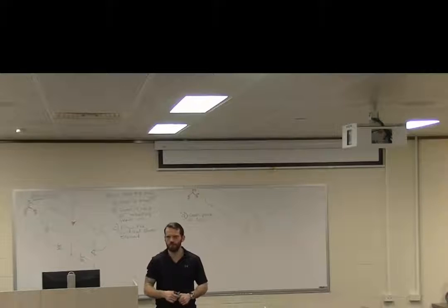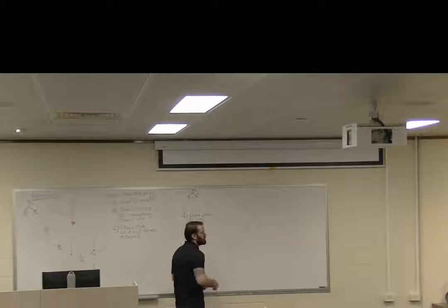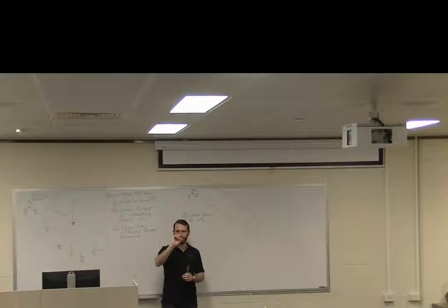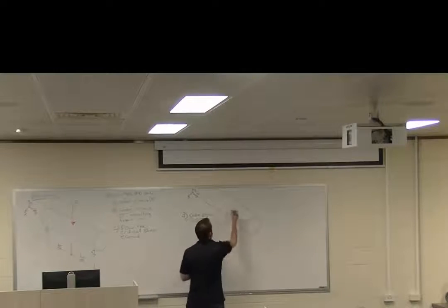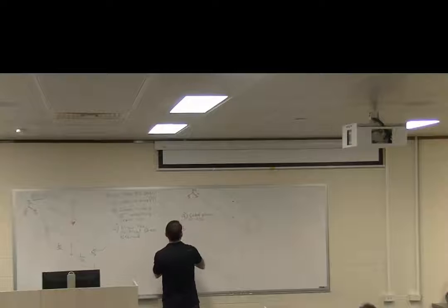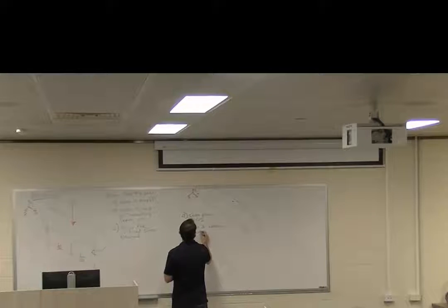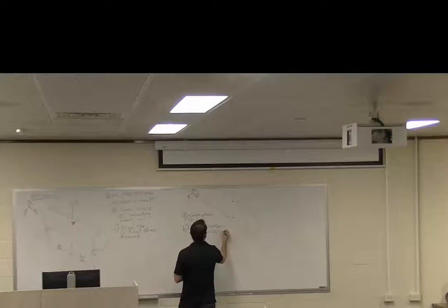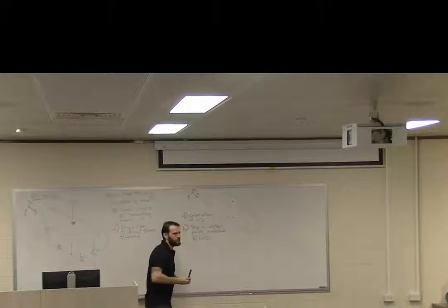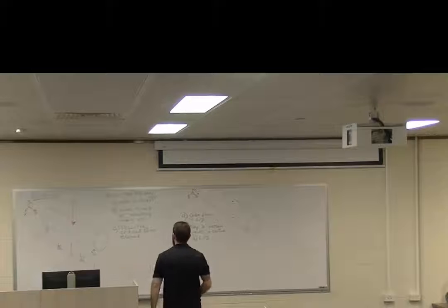Alright, B, where's our maximum bending stress? Top and bottom. At the very, very top and the very, very bottom. Is it a line? Is it a point? Is it a surface? Point? Yeah. There. And there. Top and bottom points in center at L on 2. Okay, so we have 2 singular points where that maximum will occur.